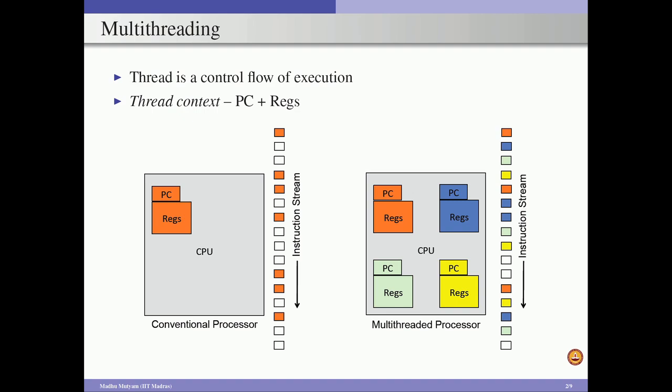Now, you can clearly see here, for example, this instruction from this software thread mapped onto this hardware context incurs an L1 miss, which is going to take 6 to 7 cycles to get the data from L2. Meanwhile, while this instruction is sending its load request to the L2 cache, and the L2 cache is going to supply the data, we can schedule instructions from the other threads onto this functional unit.